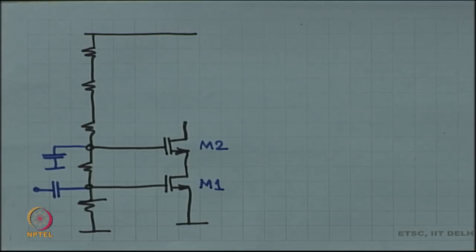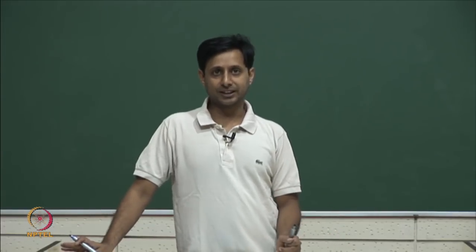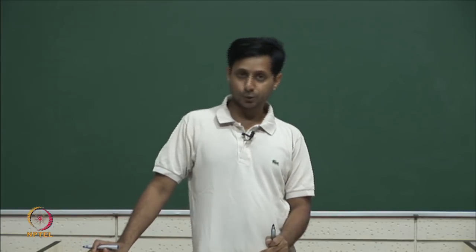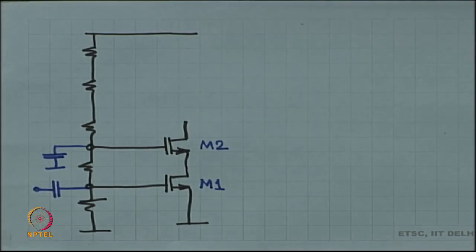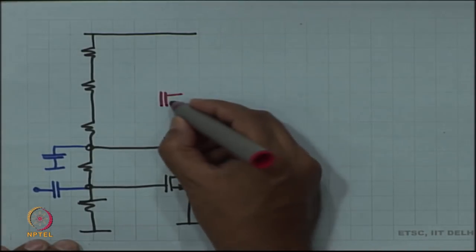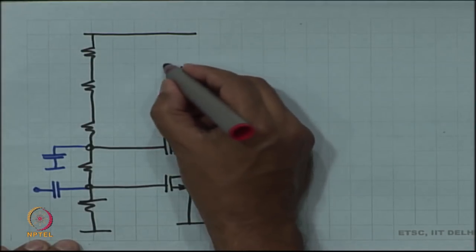The output impedance times the same old transconductance GM gives you a reasonably large intrinsic gain. But to get the actual gain as close to the intrinsic gain as possible, what do we need to do? We need to make sure that the load is also a similar very large impedance. Okay. Just having a high output impedance is not good enough, the load also has to have a very high output impedance. So, here we make a PMOS structure, and this is nothing but the load.